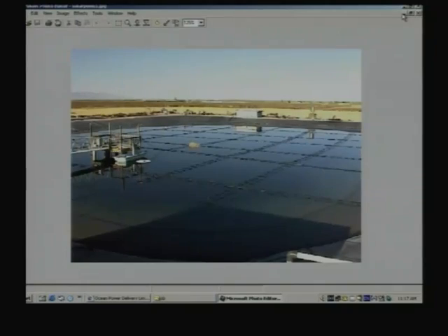So, the essential concept is where you will have a pond. The more the area, the better. You do not really need to have a large depth. It is only necessary to have the salt gradient in that depth. So, normally the depth would be not more than the depth of a swimming pool maybe, but at the bottom you will have the darkened surface, and that water is what really captures the energy.